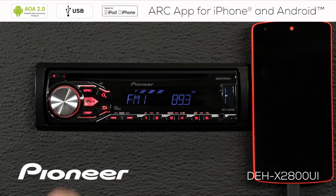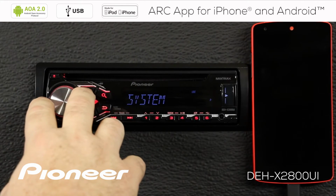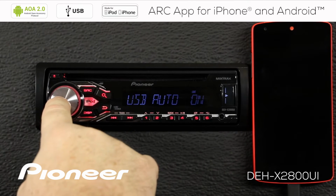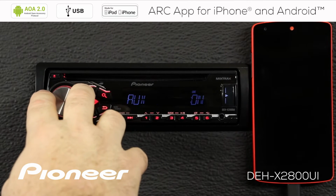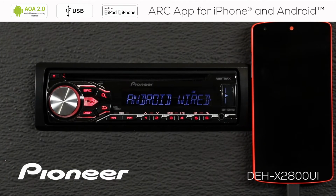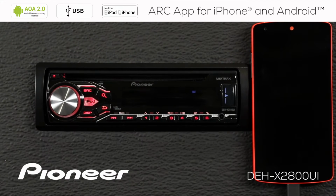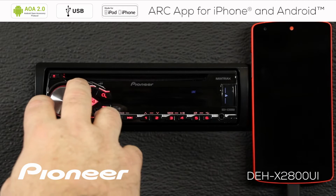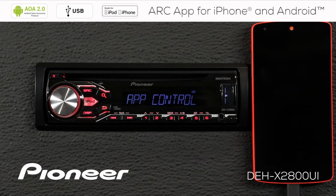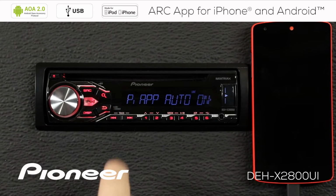So from any source, we'll touch in on the volume control, and we're going to roll along here until we find the System menu. Here's System, and press Enter, and here we want to roll along until we find the Android wired connection. So we have two settings here, Android wired: we have app control, and we have memory. We'll use memory if we're going to play back music stored on the phone. For the ARC app, we want app control. So we'll select app control and roll over to the next setting, which is to prompt the app.